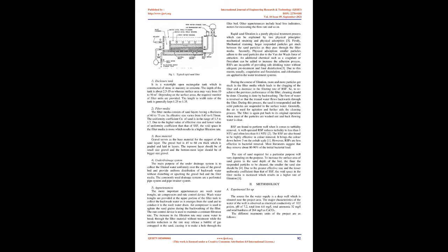tolerated. Slow sand filters, SSF, were the first effective method devised for the treatment of water contaminated by pathogenic bacteria. However effective in removing the turbidity and pathogens, it has a large land area and filter media requirement, which is the reason it was superseded by rapid sand filters, RSF.